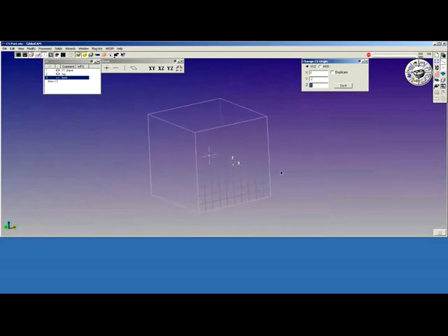Notice that I am keeping the positive vector of the coordinate system away from the cube, controlling the tool approach from outside the cuboid. All right, I'm going to build another coordinate system. This time I'm going to place this coordinate system on the back of the cuboid.